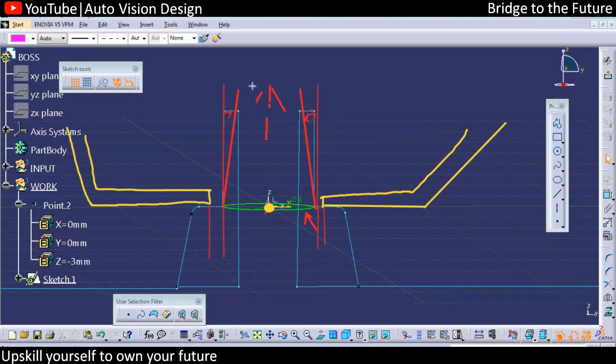Okay, so bottom is something like the bottom surface point. Here you can check, this is nothing but the surface we have. So on that surface you can select the bottom point. With respect to that, we can add the sketch, and again we can go for the draft. Okay, so here you can find whatever draft we added is with respect to this neutral face.